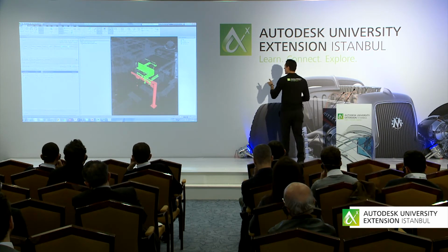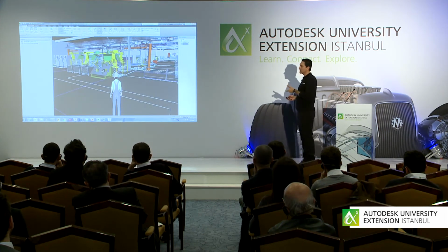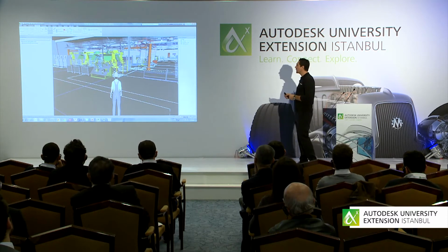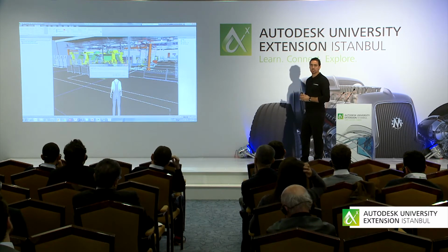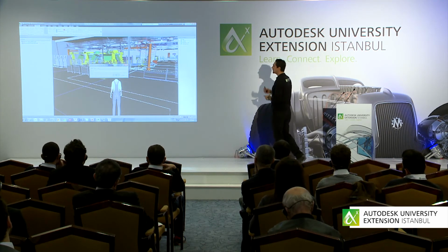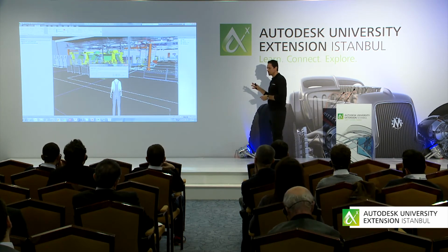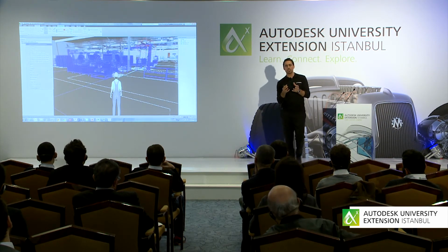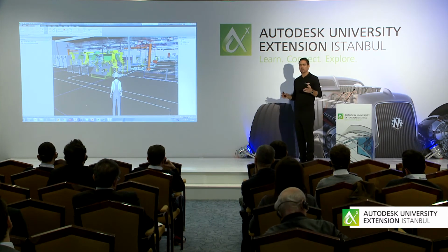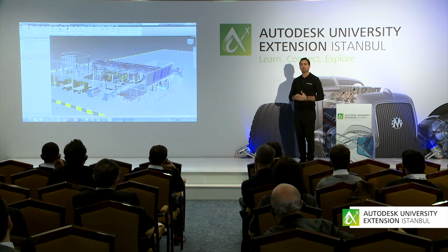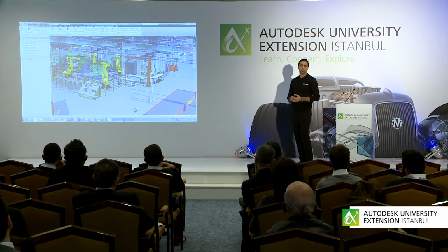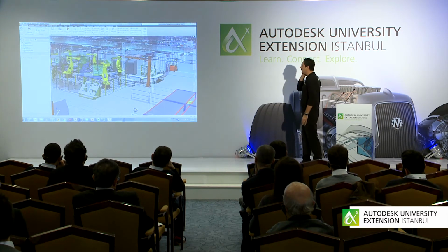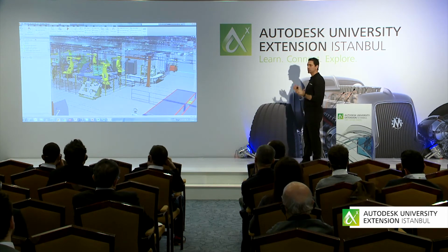So there's a functionality where you can switch back. If the structural designer of that component has put a beam in a certain space, and it's affecting the actual factory layout, there's the ability to click and switch and launch the actual environment that the structural engineer used to create that beam, update its positioning, and then switch back into Navisworks to clear the clash itself. So again, point cloud data can be brought in for existing factories.